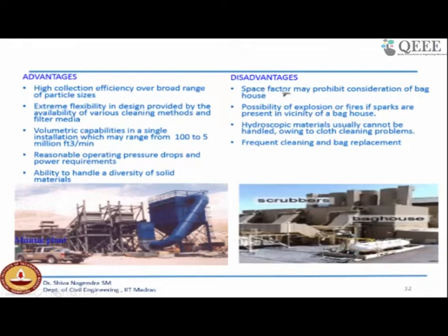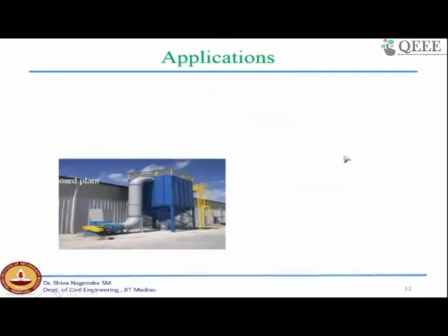So now some disadvantages. The space factor, because if you want to go for a large volume of treatment of flue gas, then you need more space. Then the other problem: in any combustion emissions, sometimes unburnt hydrocarbons will be released. If these hydrocarbons are captured within this bag house, then because of the temperature they can be subject to some explosion. If the moisture is very high, then bag house efficiency will be very low, so you need to go for frequent cleaning. Bag damage is something else you will come across.